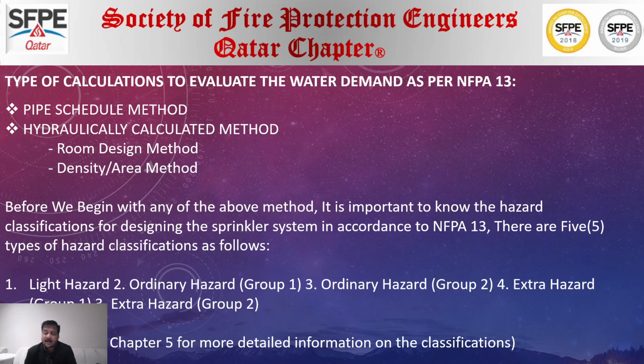Whereas the concept of the hydraulically calculated method as per NFPA 13 is based on a fire happening in a single fire area, and it is confined within the area of origin by having fire barriers. Because the NFPA codes evolved a lot from the 1970s, with the introduction of NFPA 101, which introduces the barriers, they applied that concept to the hydraulically calculated method.